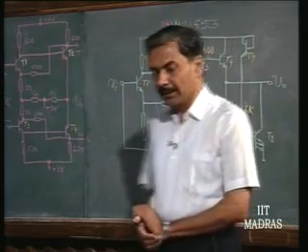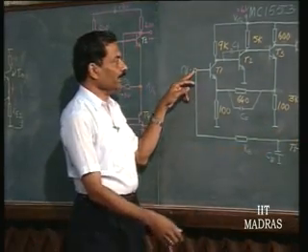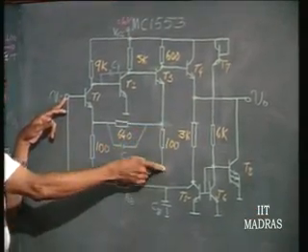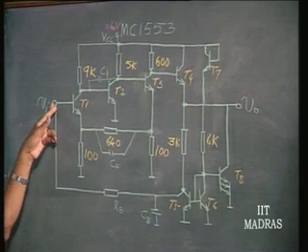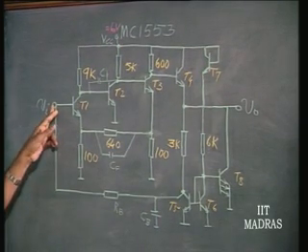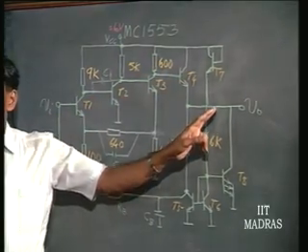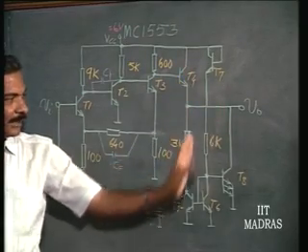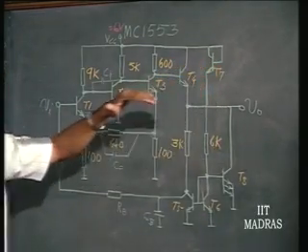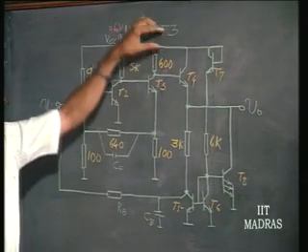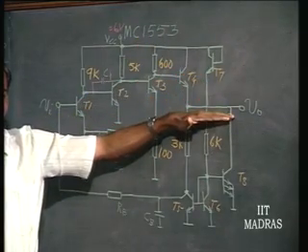And this particular thing is realized in the form of an IC here. Okay. Let us identify quickly. This is Re1, this is Re2, this is Rf. So, now you are aware of what this gain or the transfer admittance parameter is for this structure, and these are the 3 transistors which are cascaded together. Output is connected only through a common collector stage which is operating at a pretty high current. So, that output impedance, if you are taking it as a voltage, strictly speaking this is a current. This current is converted into a voltage by making it come across the 600 ohms, that is all, and that voltage comes as such at the output with low impedance.